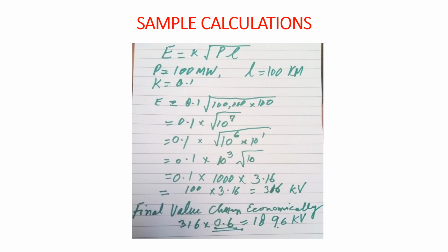A utility company may ask you, even if you get 132 kV from the formula, to connect your station with 220 kV, because they have a bigger picture and they know that in future, after 30-40 years, your station will be connected to other stations by additional lines, and in that case the short circuit level may rise and the load flow may also increase on the line which you are assuming.